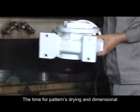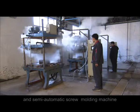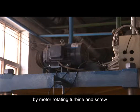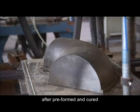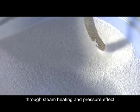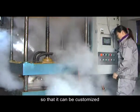There should be pattern drying and dimensional stabilization for some time. The main equipment includes hydraulic molding machine and semi-automatic screw machine. Semi-automatic screw molding machine is driven by an electrical machine. The EPS beads are filled into the mold after being preformed and cured. The foam beads bond to form a pattern through steam heating and pressure effect, and then it is decompressed and cooled by water so that it can be shaped.